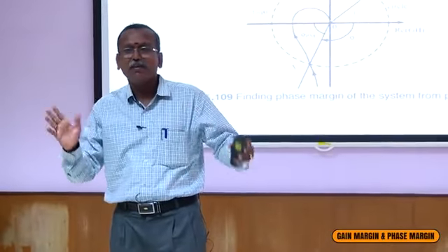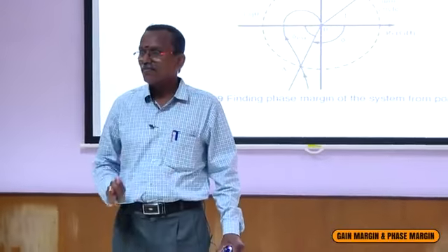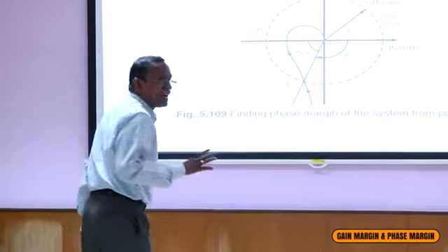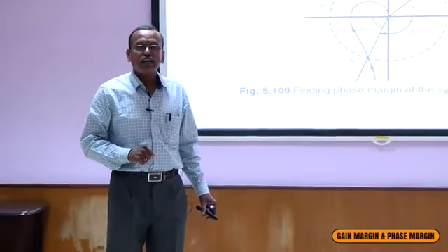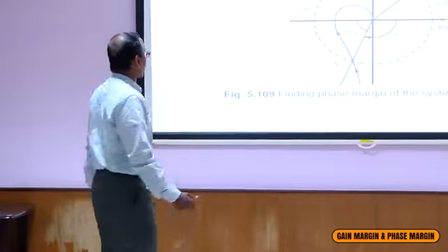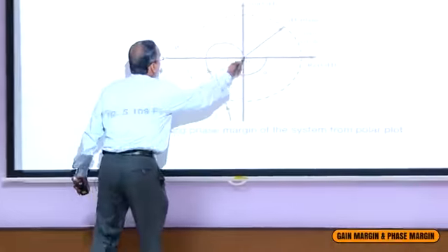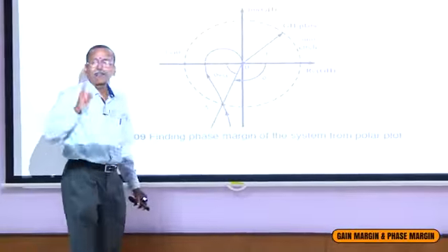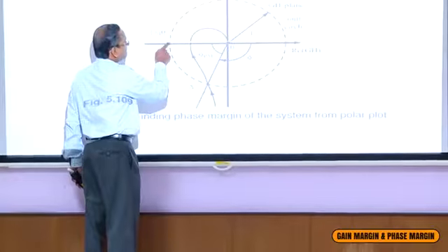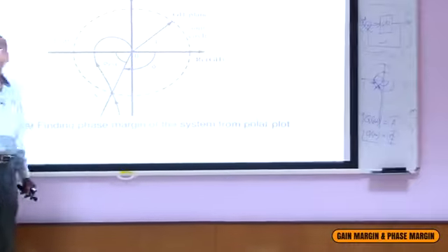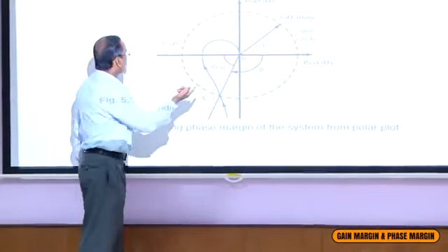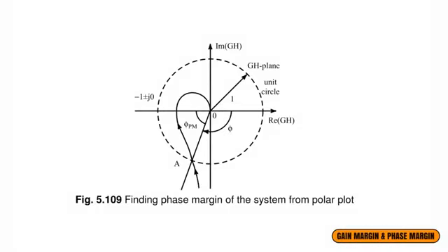So that is the maximum limit. After that the system becomes unstable. If you further increase, the system becomes unstable. So the stability of the system can be derived from this phase plot, the frequency response, the Nyquist plot. If the response passes through -1, the system exhibits sustained oscillation. If it does not enclose this -1 plus or minus j0, the system exhibits a stable response. If it encloses this -1, if it goes beyond this -1, the system becomes unstable.